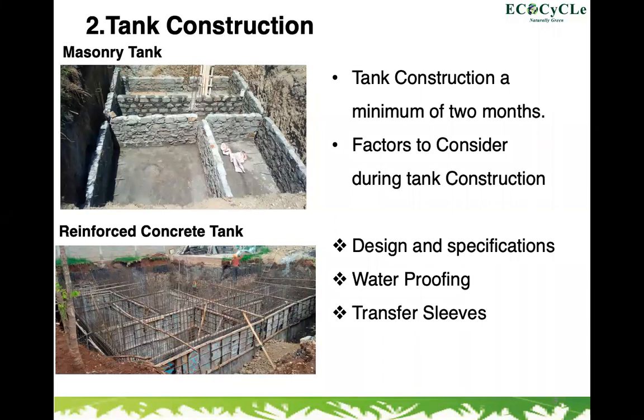For those who are not engineers or technical in this webinar, maybe let me explain. The invert level is the difference between the last manhole and where the sewage now enters. Reason being, it has to enter through gravity. We do not pump sewage from the household into the tank, it flows by gravity.